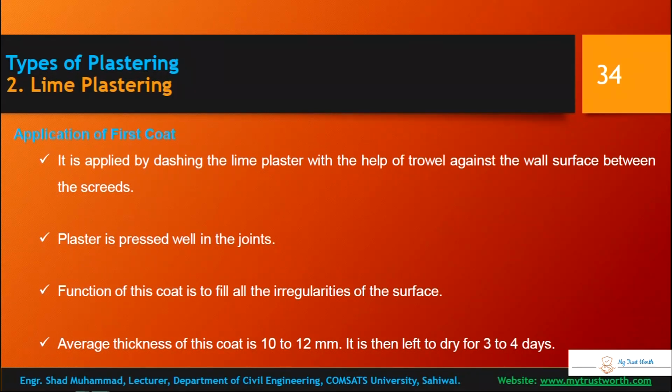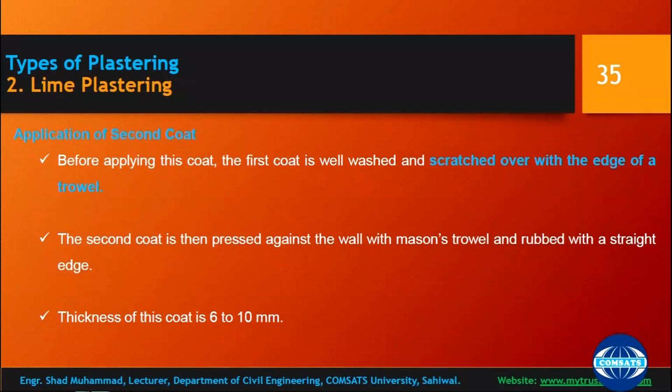The function of the coat is to fill up the irregularities of the surface. Average thickness of this coat is 10 to 12 millimeters. It is then left to dry for 3 to 4 days.